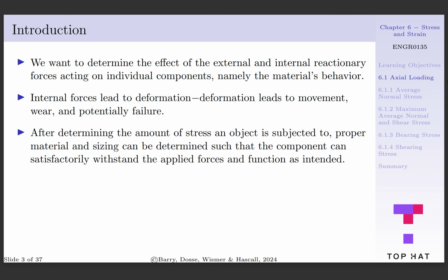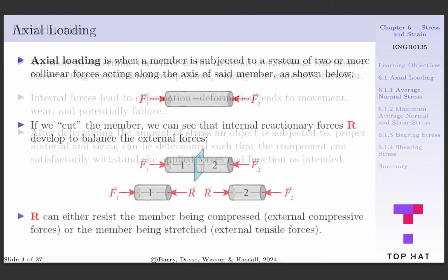We want to determine the effect of the external and internal reactionary forces acting on individual components, namely the material's behavior. Internal forces or stresses lead to deformation, which in turn leads to movement, wear, and potentially failure. After we determine the amount of stress an object is subjected to, we can determine the proper size and material for a component such that it can withstand the applied forces and function as intended.